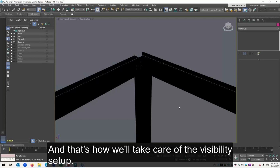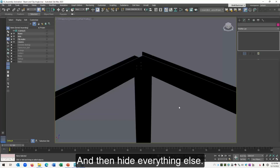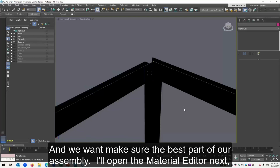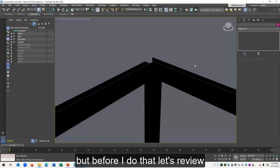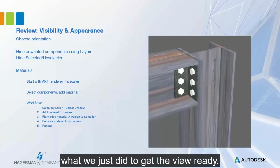And that's how we'll take care of the visibility setup. We'll orient the model how we would like to see it, and then hide everything else. Next, we'll deal with the look. Max is known for its ability to show things with realistic materials, and we want to make sure that that's part of our assembly. So I'm going to turn on the material browser next. And actually, before I do that, I do want to review real quick what we just did to get the view itself ready.